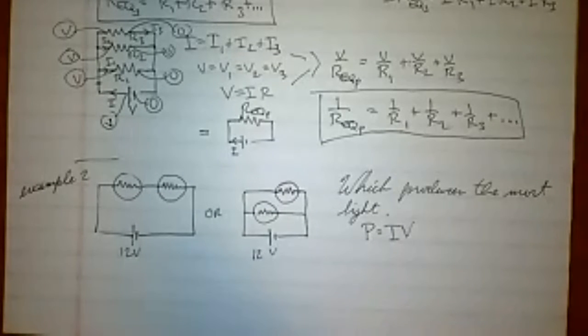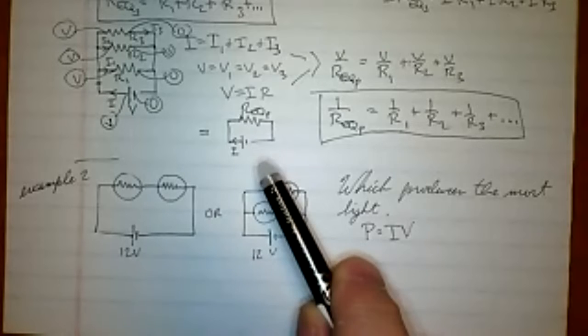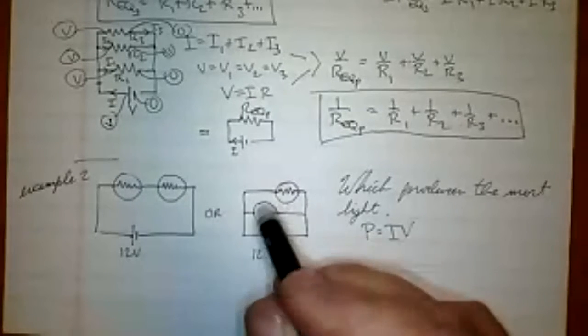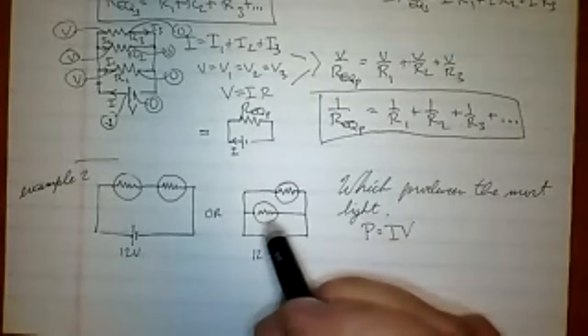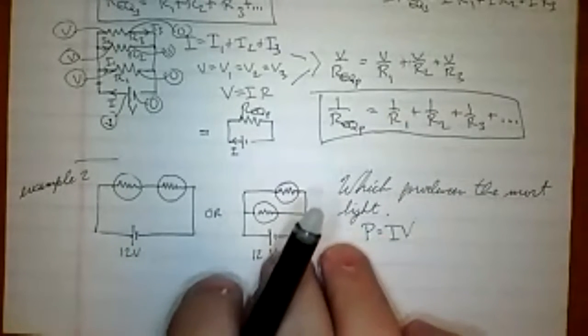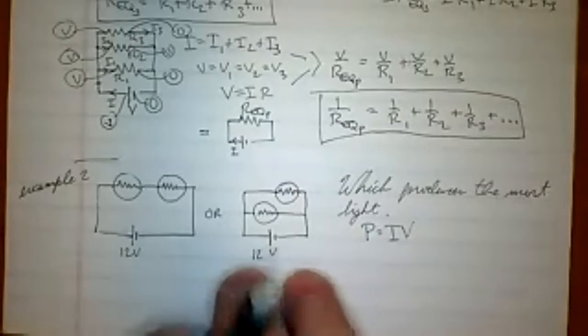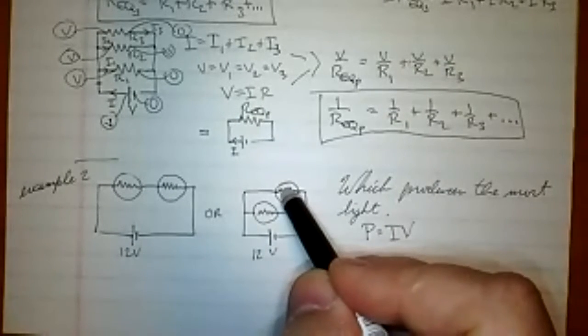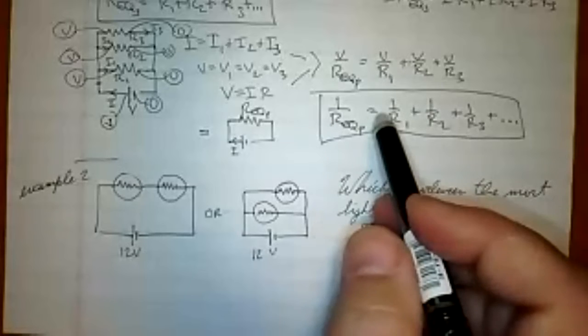Putting them in parallel is going to lower the resistance, which would allow for more power. Is that correct? Yeah, possibly. I'm going to actually put my money where my mouth is by showing you, but yeah, you're all asking exactly the right questions, making exactly the right statements. You're realizing the reality of the problem, which is, okay, here, this is going to make a smaller resistance because resistances add as reciprocals.